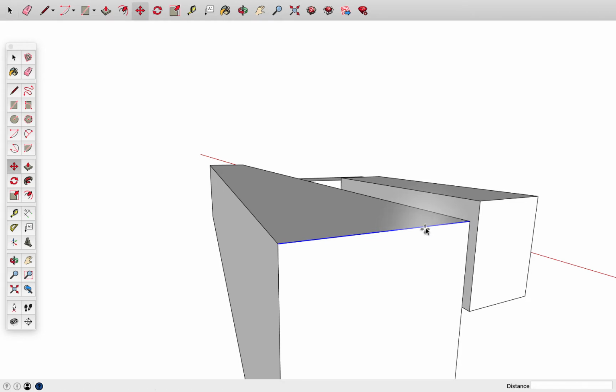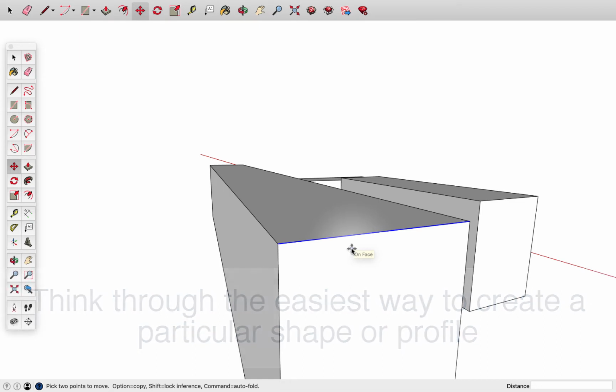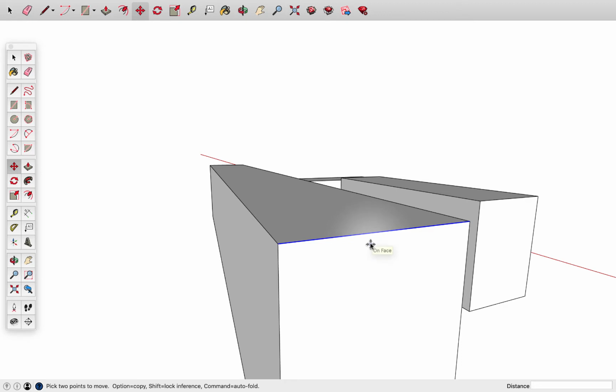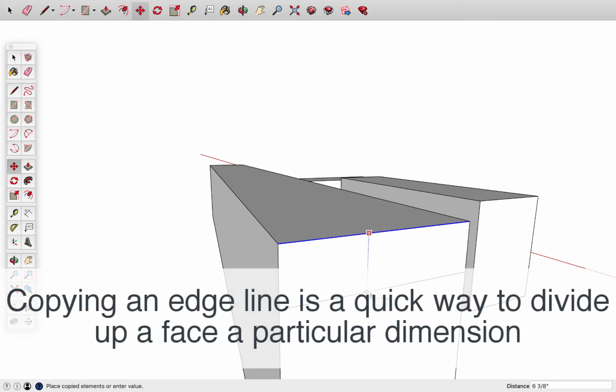I'm going to just draw the profile along the edge here and push-pull it down. That way I can really think about what my countertop is going to look like. So first of all, I'm going to select this line. I'll use the Move command and tap Alt or Control on a PC, and I'll copy it down. And I'm going to go with a 30-inch countertop.